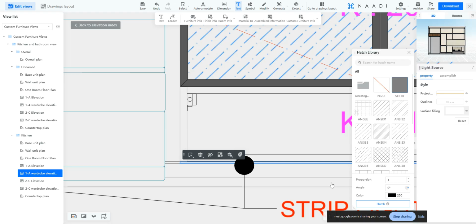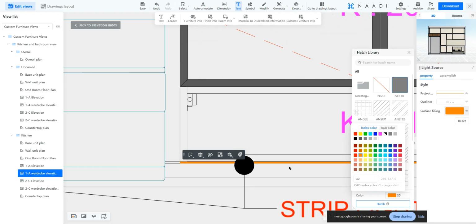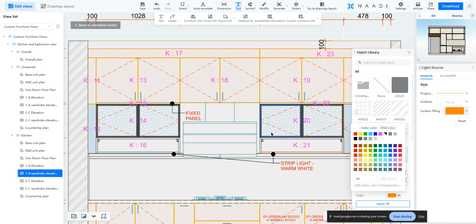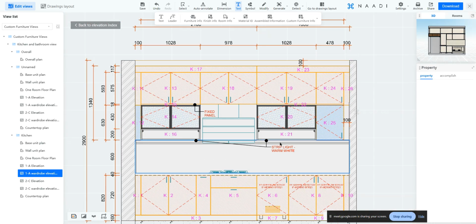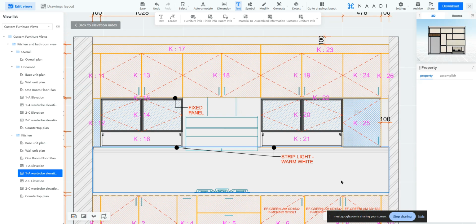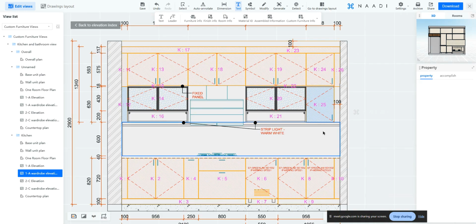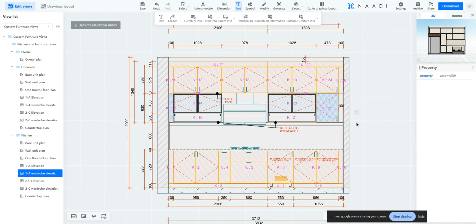Right now I'm selecting this column and I'm just changing it. But if you just use select similar, you can define it. So to this precision, you will be able to define the factors here. So this way, if you are able to select something in your 2D drawings, you should be able to change the hatch line color and take it forward. This is how you should be able to manually add a hatch to a drawing. So yeah, all these factors could be done.